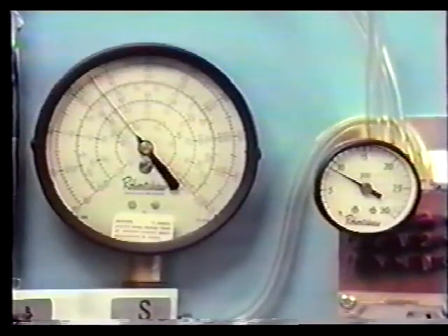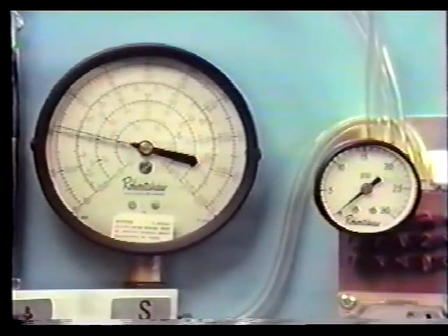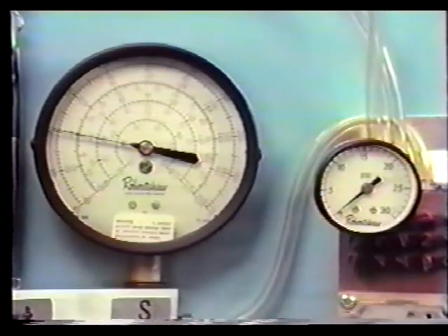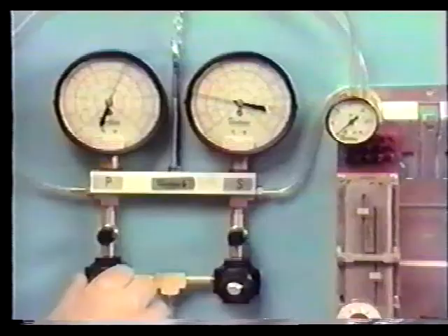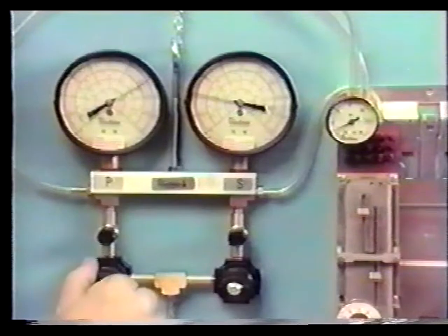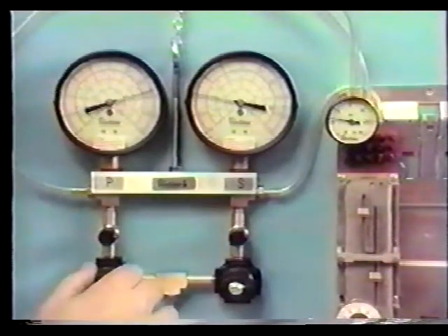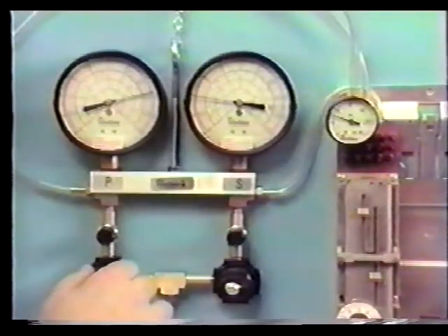You can simulate a change in outside air to check the authority setting. Change the secondary input to represent 5 degrees. The branch line pressure will drop, which will open the normally open heating valve to increase the temperature in the pipe. Now, increase the pressure on the primary input slowly until the branch pressure is back to 9 psig. The primary input gauge should read approximately 190 degrees.